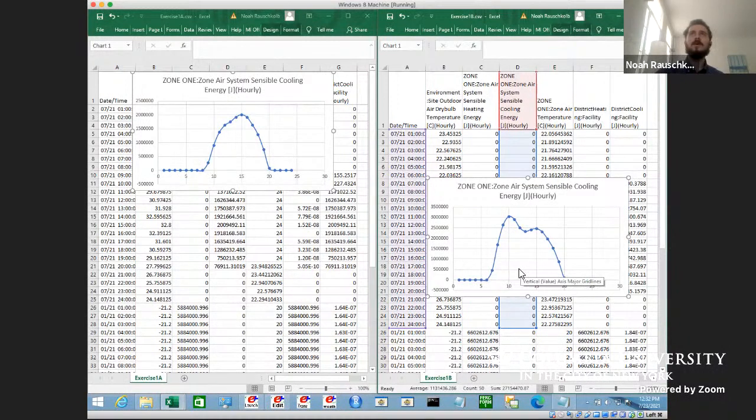Anyway, back to where we were. I added the one window, and you see how it affects the air conditioning loads and the heating loads. The heating load is just a 15% increase in the steady state for this EPW. With the air conditioning, with the east-facing window, you get a different shape to the load. And if you added a west-facing window, you'd also have it peak more over here.